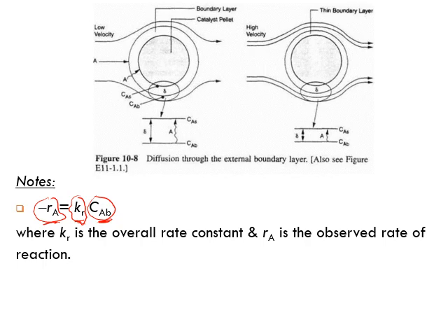What happens if the flow goes faster? So here you have low velocity. Now the velocity is higher. The flow velocity is higher. What do you notice? Well, you notice that the boundary layer becomes smaller, right?